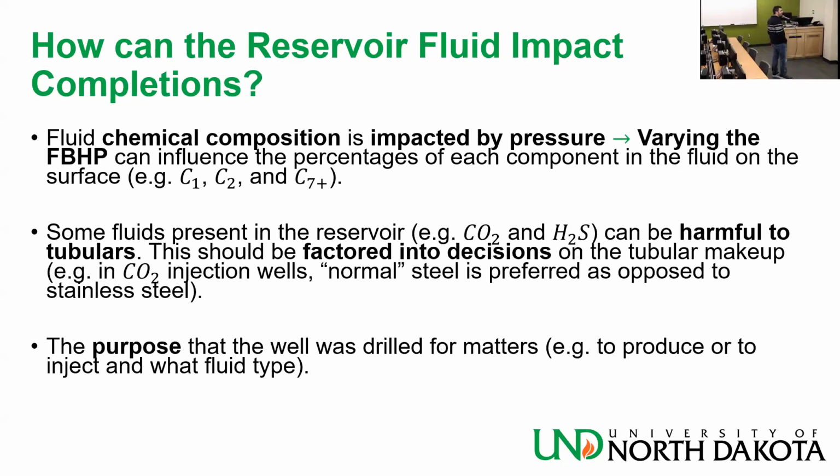The purpose that the well was drilled for matters. Is it to produce or to inject, and what fluid? You may have drilled a well that is going to be used for water injection or CO2 injection for EOR. That means it's going to be injecting CO2, but not at high pressure. But if it's for CO2 storage or sequestration, then it needs to handle a lot of pressure as well. There will be injectivity issues.